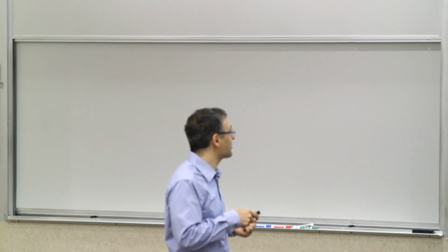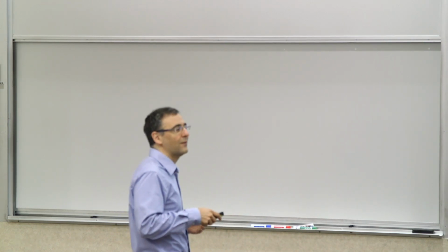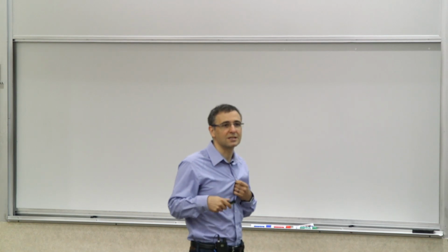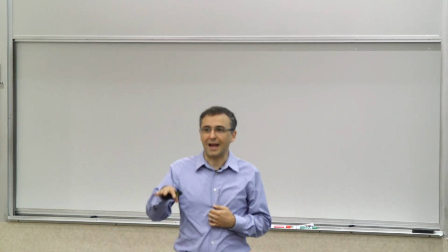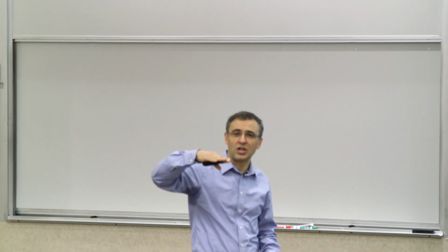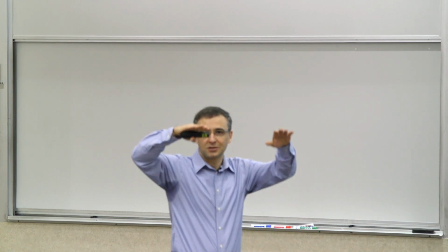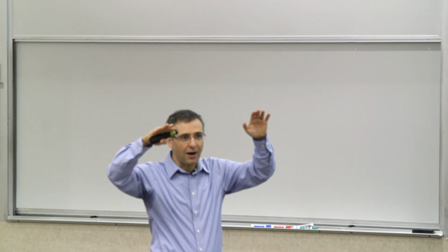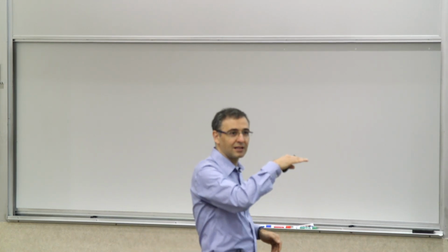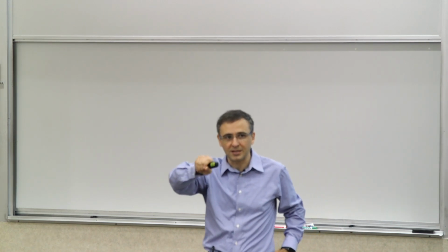The good thing it does is that it allows you to modulate the amplitude too, if you needed to do that. The question is how fast you can do this, but you can provide some amplitude modulation. You remember we had the scaling rule in the very beginning, that if you scale the VDD of a power amplifier by a factor of lambda up and down, we could scale the voltage and current and therefore scale the power. So by controlling this voltage, you can scale the power. In general, with switching power amplifiers, you can control their power by scaling their voltage.